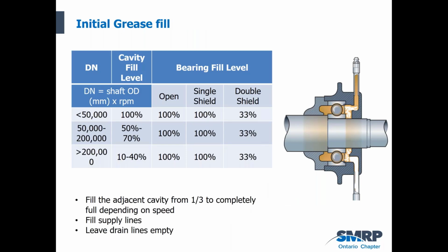But the other factor with grease in particular is not just getting the right lubricant selected, the right viscosity selected. It's really more about how we adequately grease that bearing. And more grease lubricated bearings fail because of inadequate greasing than those that fail due to poor lubricant selection.